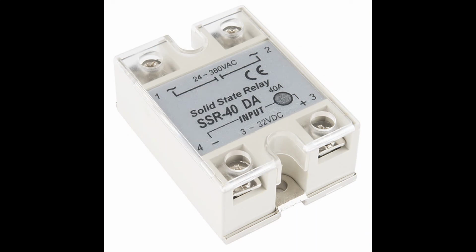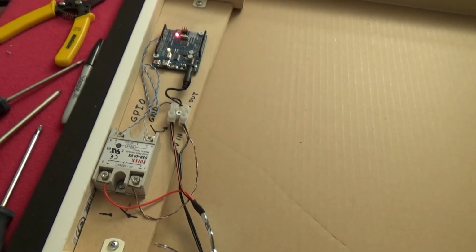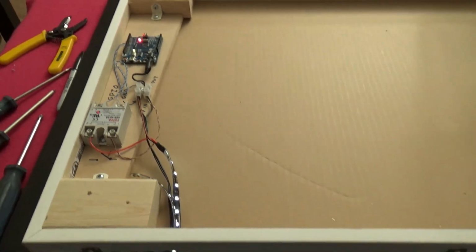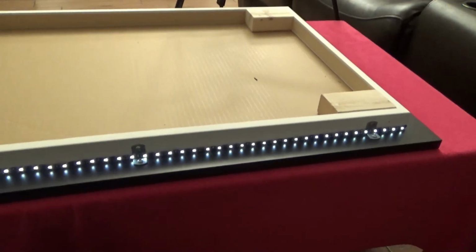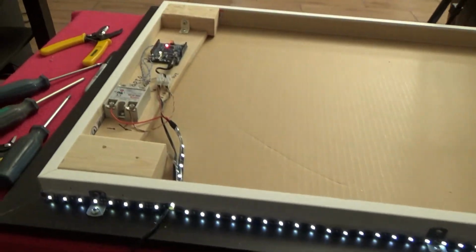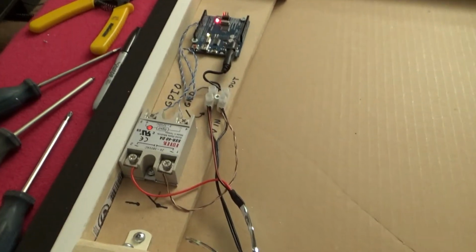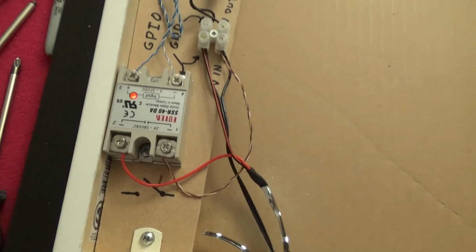There are several forms of relay. Some are mechanical, others are electronic. The semiconductor relay does not have the mechanical part, which makes it a silent relay. However, attention must be paid to the output current because some models operate in DC while others operate in AC. If you use an AC output model and plug in a DC power supply, it will turn on at the first input signal and will remain on until you turn off the output current.